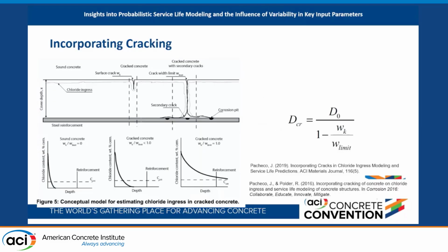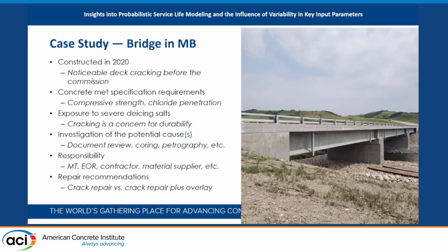But for the most part, it's going to be in the order of maybe 400 microns to 500 microns for the projects that have been involved where we have cracking problems. And one of them is, since we're in Canada, I brought a Canadian project. This is a bridge in Manitoba that was constructed in 2012, and even before commissioning, there was cracking on the concrete deck. And the specification was very good.